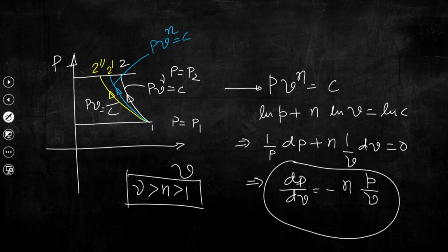Hence, work input to the compressor, if the compression process follows the reversible adiabatic one, would be high, and the minimum work would be needed for the reversible isothermal compression, but we have discussed that